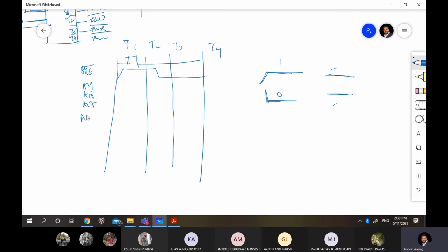After that A19, then A18, A17, A16, A15. Try to understand, these will have their own address, because as I told you, in a memory read, take the instruction MOV AX, [2341]. We are just reading from memory, right? We are going to this particular memory location, reading from there and bringing it to the microprocessor. That is what a memory read is, and that is all that is happening here.